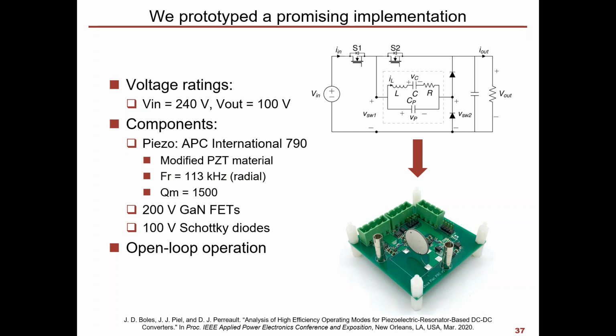These are high specific impulse, low thrust applications which need very high voltages to operate. But the challenge is that satellites have a very low voltage power supply, somewhere in the order of 28 volts. So we need to boost them all the way to thousands of volts.